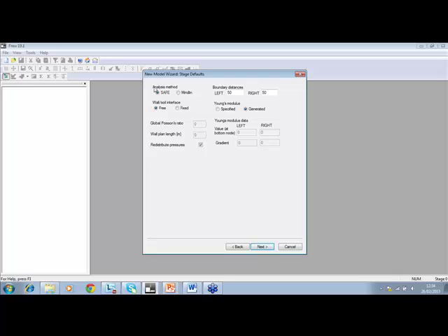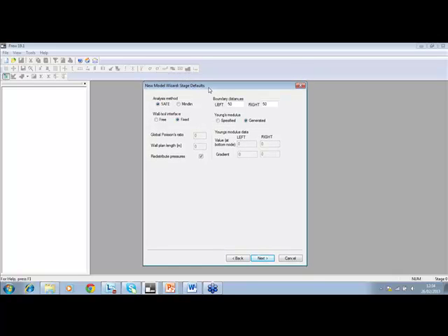Okay, so I'm going to use the safe method for analyzing and for calculating the stiffness of the soils. So the wall soil interface with the safe method for this would be fixed. And if you want to understand how this works, this is connected to the safe method. You should check it in the user manual. In terms of boundary distances, I've just set a reasonably large distance here.